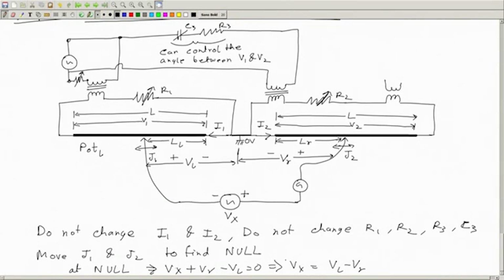Okay. So, let me just conclude this video by summarizing it in brief. What we have to do is first decide the per unit length voltage that we want to have. Then we set the standard, connect the standard cell to the potentiometer, keeping in mind the chosen value of voltage per unit length. Find the null, that is calibration of potentiometer 1.